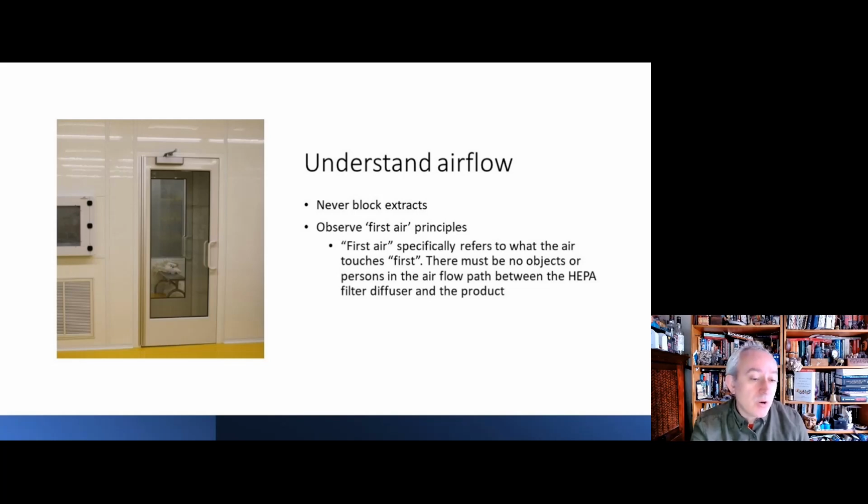It's also important to get to grips with the concepts of airflow. When you're working in unidirectional airflow devices, one, you have the minimum number of items within that device. Two, you never put anything near the back. You never ever block the air path. So you have to look at the differences between vertical and horizontal airflows.